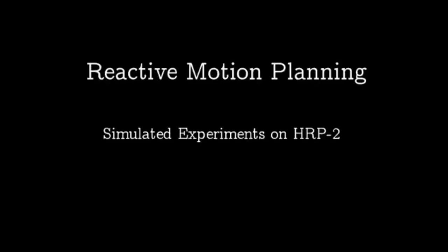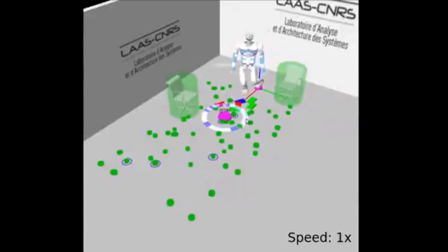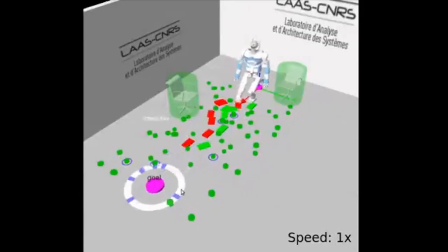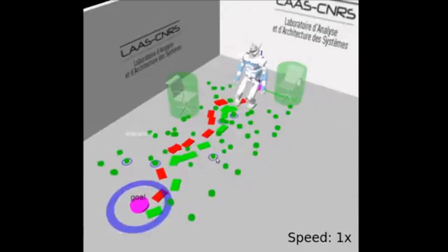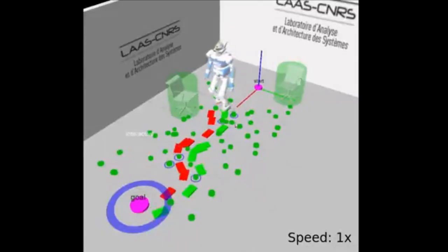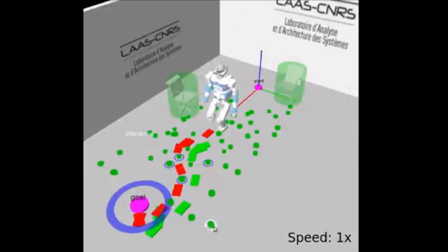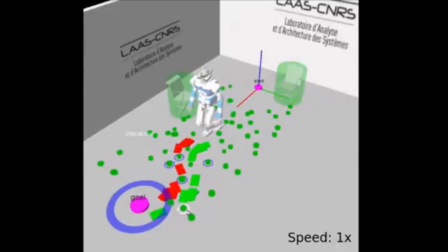Maybe also to show a video of some of his research, which is maybe now quite old, but still interesting because it's this very high-dimensional humanoid robot which has to move in this kind of rough terrain. And for that, you really have to plan where you want to put the foot. And once you decided where to put the foot, you also have to figure out what to do with all the joints in order to not tip over. And you can see here users can change things interactively, and then the motion plan also reacts to it, which means you have to be fairly fast. You can't spend hours on finding a solution.